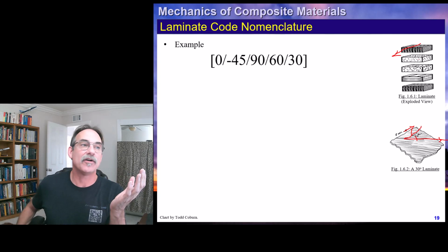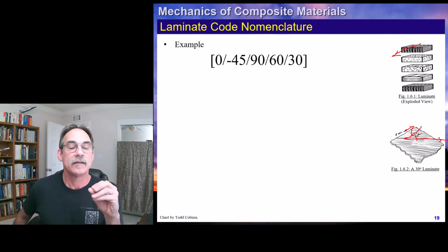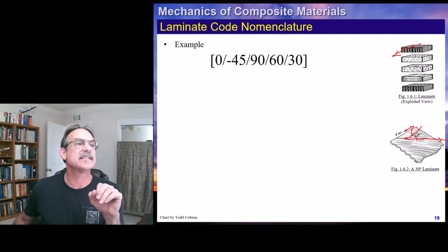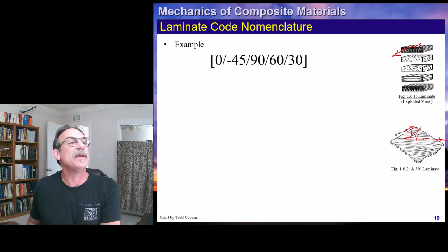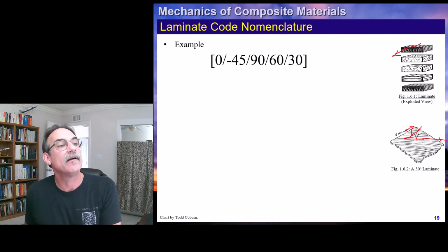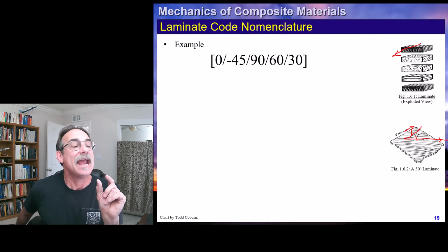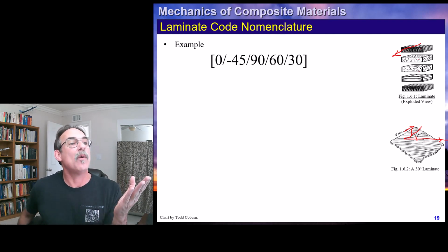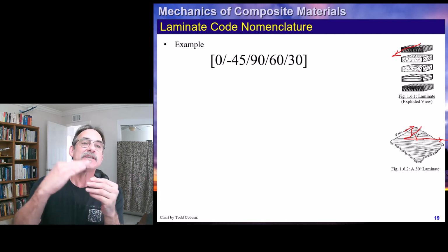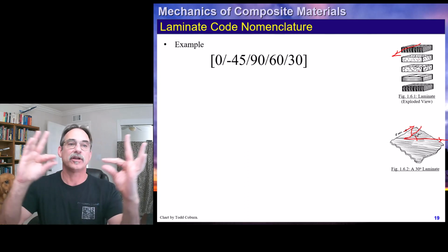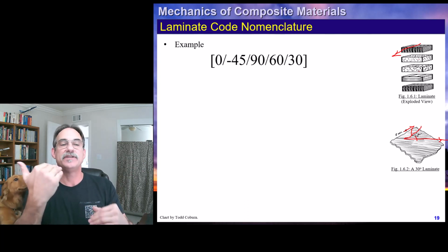This looks like a pseudo-isotropic material made of little powders or flecks or flakes or grains in another matrix. And the next layer looks like we have little short fibers, which are all mixed together. And then we see that weird looking one. Actually, that's what these fibers look like if they're off at an angle. Now, if they've been in this direction, they might look the whole length. If they're going in the 0,